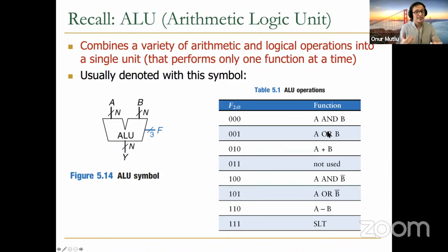So this way, if you have an instruction that says AND, you know that you should give a control signal that specifies the AND in the ALU, right? Hopefully that makes sense. Now, you can imagine how if your instruction is an add instruction, you'd better make sure that the control signal in your ALU is 0, 1, 0.